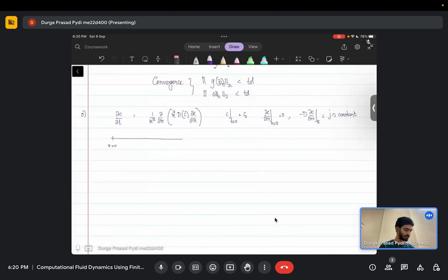For the unsteady part, I think it is straightforward. The only thing I want to point out here is that until now, when we have fluxes on these cells, we start by considering the faces, and then we take the nodes. So our unknowns are essentially the values at the nodes. Say this is my Cn minus 1, the value of C at the n minus 1 node, and this is my face value. This is my east boundary. How do I calculate the value at this particular east boundary if I know the value of Cn minus 1?